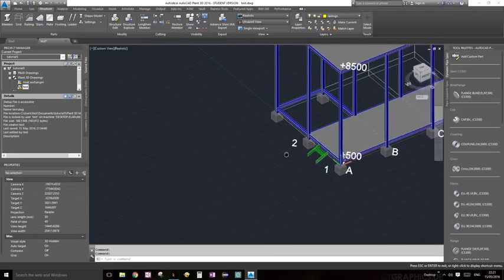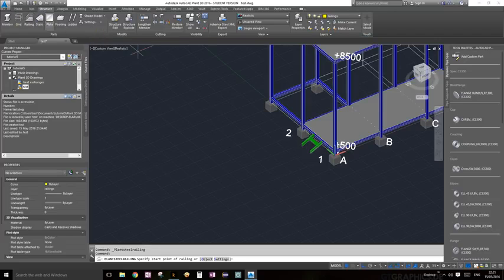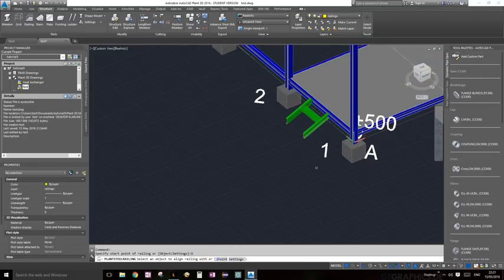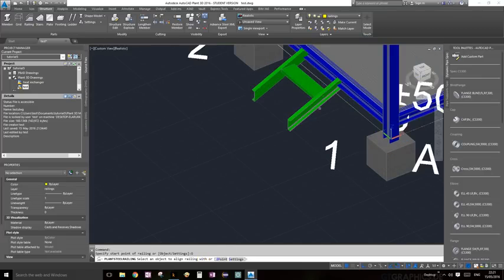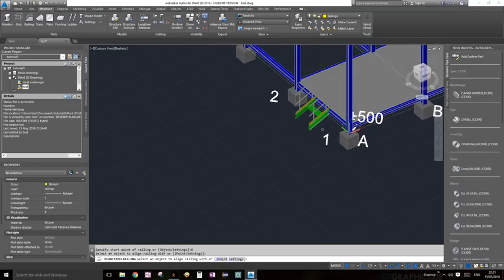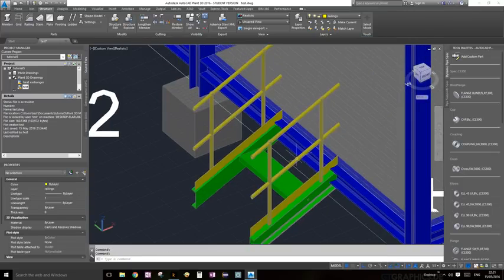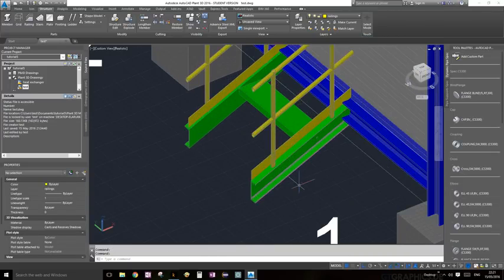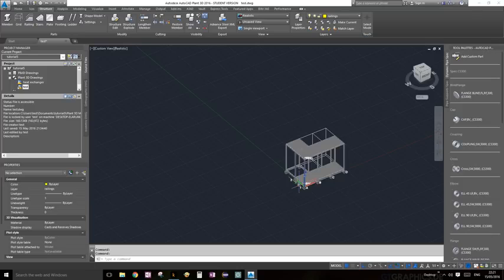Okay, let's get started. So click on railings, and the first thing it's going to do is ask you to specify the starting point. Instead of that, we're going to go to the command line and click object, and this is a very handy little tool. Just click on the object, in this case our stairs, and bam. How easy was that? Look at that. I'm going to skip to get out. Now we have railings for our little thing, and that is pretty easy.